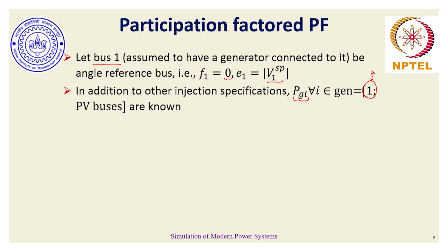But from a power flow perspective, we intentionally don't use that PGi, because if you recollect our discussion on the classification of buses, the slack bus discussion specifically, if all generators become specified, it is not necessary that all generators together would match the load. Even if the generation-load mismatch is 0, the network will have losses. So one of the generators has to become free so that it can also account for the system losses while the load is being met. That's the reason why, for the slack bus, we don't consider PG in the conventional one slack bus case.